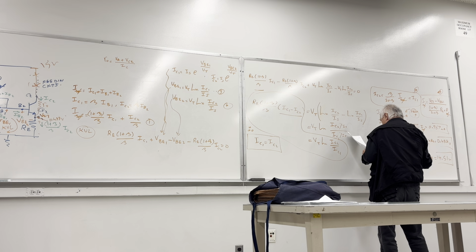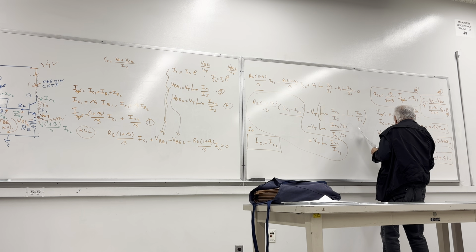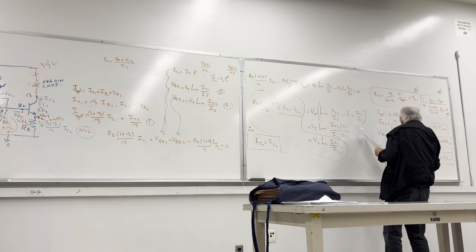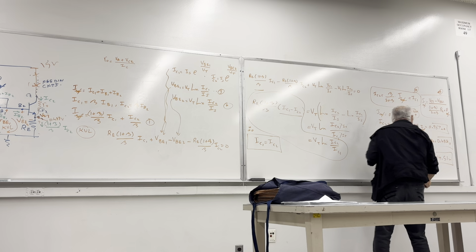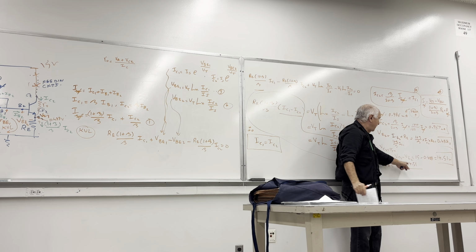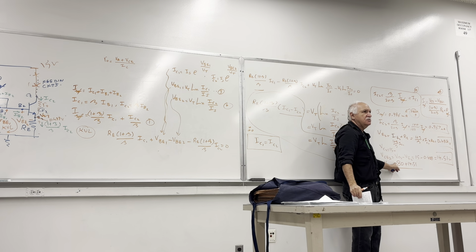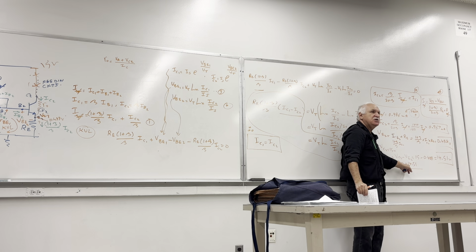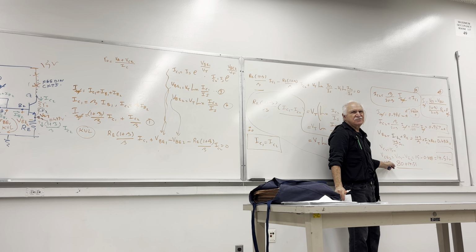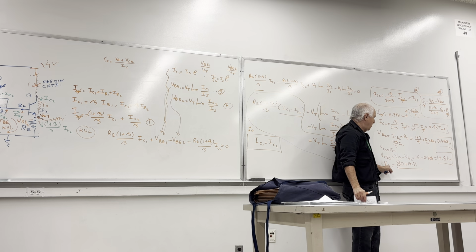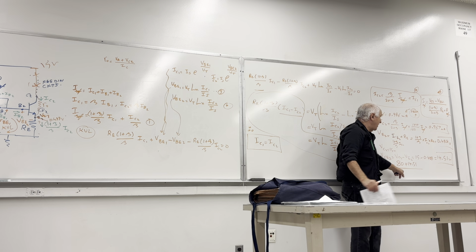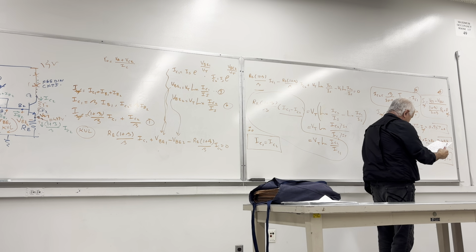Here, RO adds up to be 80 volt for VA plus 14.51 for the VCE. And you notice the 14 is pretty small compared to 80. Do you see that? So actually VCE doesn't play that much of a role. It doesn't affect the value of RO. Divide by IC, yes, IC is important there.